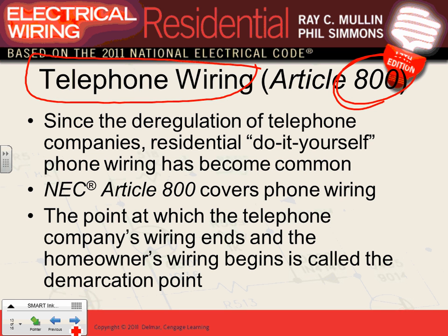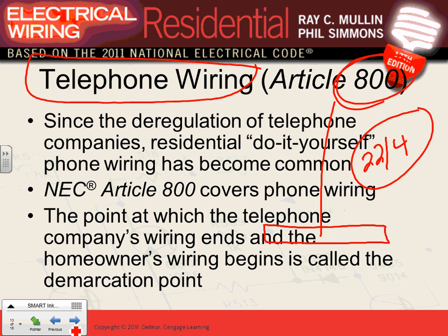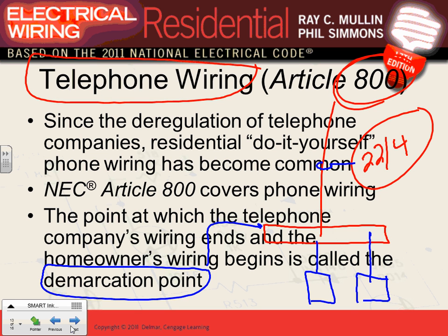Okay? So I believe it's 22-4. 22-4 is the cable that you get. 22-4, so gauge 22, 4 conductors coming into your house up to the point called demarcation point, right? That's the phone. Now we move into the phone. Here's the phone, right in here. This is where the utility stops, right at this point, demarcation point. My demarcation point is right here. This point is called demarcation point. They stop right here, and then from there, what do you do? From there, you can go for your phones, and you have either home run or daisy chain.